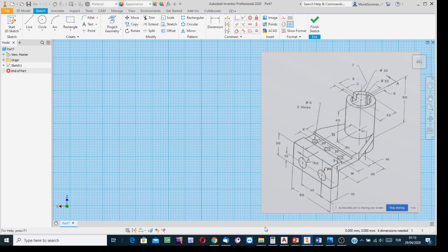Thanks to experience, having a look at the photograph or the pictorial figure of the object illustrated on the assignment sheet, you can say something. Well, this is my plan. I'm going to create the model of this part first, and then using the further adding technique, add the cylinder, add this rectangular prismatic extension, and then change the method. Instead of adding, start using cutting. Create this channel, create the holes, etc., and then finish. This is my plan.